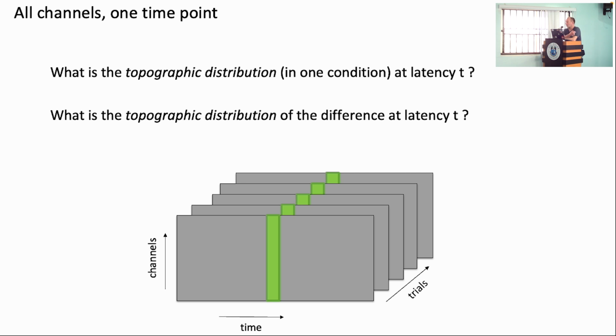So we've been working with an 8-channel EEG amplifier, with a 32-channel EEG amplifier, and with a 64-channel EEG amplifier. And in general, I would say source modeling techniques, like I'm going to explain in this lecture, don't really make that much sense if you do this on an EEG system that has fewer than 32 electrodes. So from 32 electrodes upwards, I would say that these methods start working. But the more electrodes, the better source modeling techniques will work.